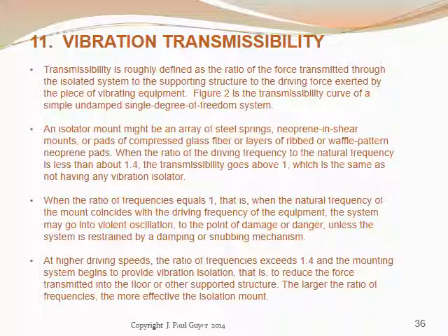Usually the driver, the operating equipment, moves so quickly through this unique speed condition that there is no danger, but for large, heavy equipment that builds up speed slowly or runs down slowly, there is a special problem that must be handled. At high driving speeds, the ratio of frequencies exceeds 1.4, and the mounting system begins to provide vibration isolation. That is, to reduce the force transmitted into the floor or other supporting structure. The larger the ratio of frequencies, the more effective the isolation mount.